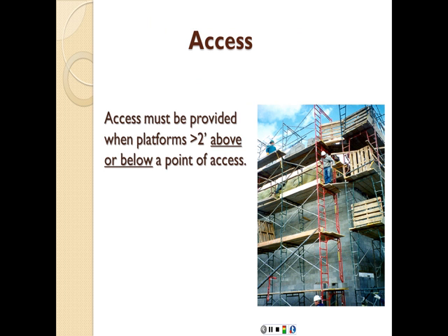How are we going to access these scaffolds? This one looks like a good scaffold. It's wide enough. It has the ladder-like access tool. It's properly braced. It's fully planked on the working surfaces. Solid wood, not plywood. And it has, in this case, something that looks like a guardrail and mid-rail here. So this looks like a good scaffold.